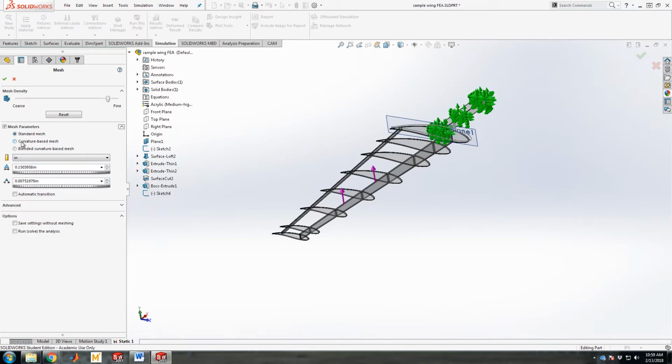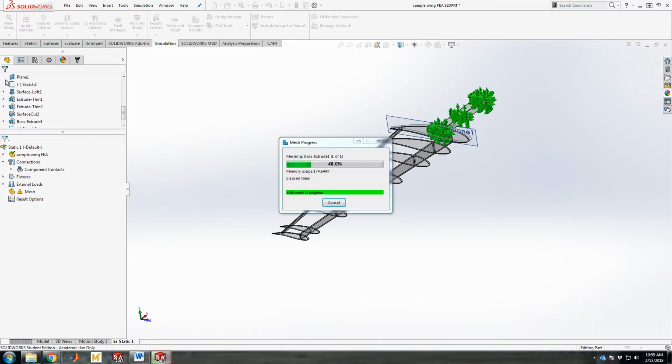So we want to go down to, I think to get this to work in the past, I'd use a curvature-based mesh, which will start applying more and more cells as a surface becomes more and more curved. Let's do 0.2 inches as the maximum size. Notice it automatically resizes the smallest number of elements in a circle. Okay, so that's the scaling. That should be plenty enough to get this thing going.